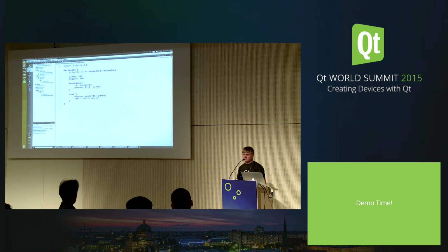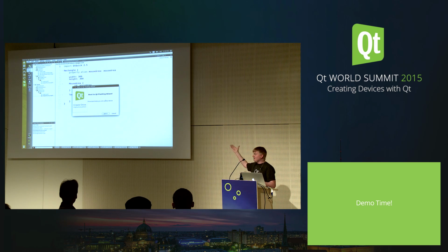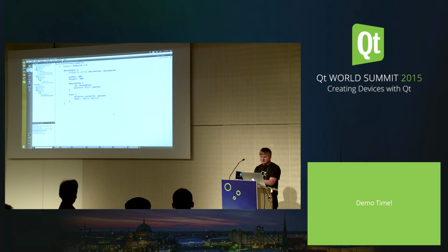The only thing that I've done on my side is flash an SD card with the image that came with this kit. We have a flashing utility where for any of the installed reference images you have, you open up the flashing utility, and you get a boot wizard that says, put in your SD card, what image do you want to flash to it? And I picked iMX6, Boundary Devices iMX6.